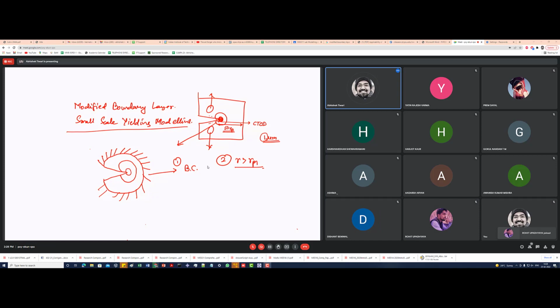And when you ensure that, not just larger but sufficiently larger, at least 10 times larger than your plastic zone, not 50 times but 10 times, so 10 times is still smaller. When you ensure this condition, then you are ensuring that your boundary condition is going to follow theory of elasticity, right? Because plasticity is contained within, so you can apply the boundary condition using the theory of elasticity.